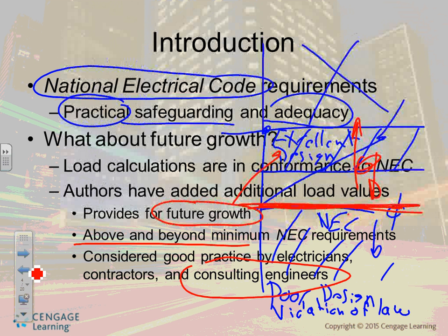Now you go a little bit lower. Well, there are 2 pieces of equipment by each other. Can I group them together in 1 pipe? Yes. Now you went slightly cheaper. You're not violating the law, but you went cheaper, right? Cheaper pipe. You put 2 circuits in 1 pipe. Is it violating the code? No. Cheaper. So that's what the contractor tries to do: group them together and shoot for the cheaper installation.